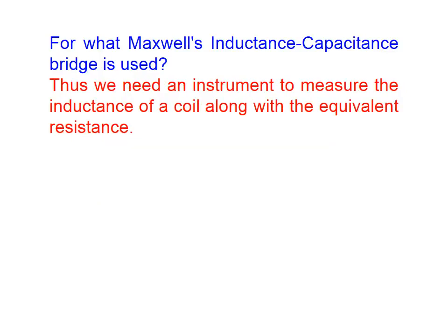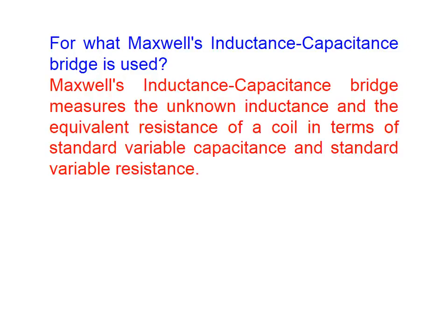Thus, we need an instrument to measure the inductance of a coil along with the equivalent resistance of this coil. Maxwell's inductance capacitance bridge measures the unknown inductance and the equivalent resistance of the coil in terms of standard variable capacitance and standard variable resistance.